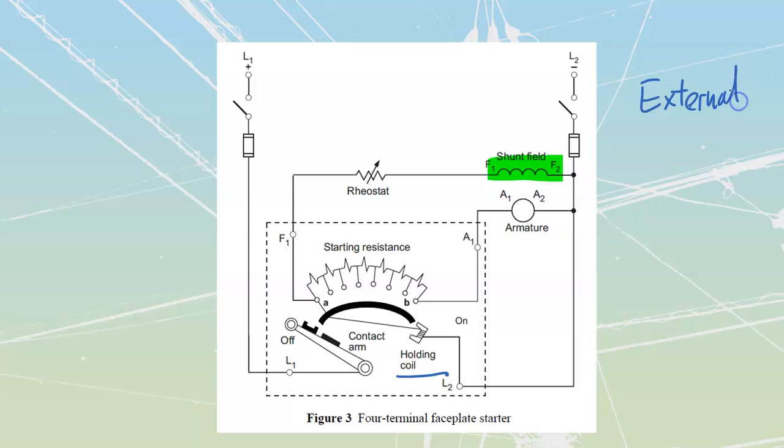The best way for us to do this external speed sensing is we are going to use a centrifugal switch, which is just going to be a switch which has got a special set of flyweights. It's going to be mounted to the motor shaft, and if it gets too fast, it's going to pop open a set of contacts, which we will then use to de-energize all of this over here. We're going to cover centrifugal switches later on once we go into AC. Right now, we're just going to say that there is such a thing as a centrifugal switch, and that it would be incorporated somewhere upstream.